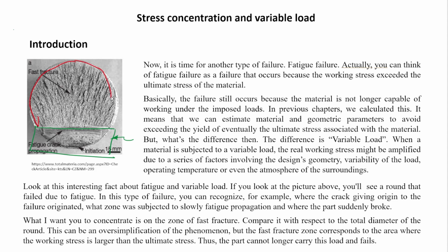So what happens is that when this shaft is working, fatigue failure starts. We don't know at the moment why it appears in the material, we'll see later, but it starts failing because of fatigue. And then this whole piece of the shaft has a different surface finish than the other one. Failing means there is a small crack here. They're going to see later that it appears also there. And this small crack keeps growing and growing until it reaches this level here.